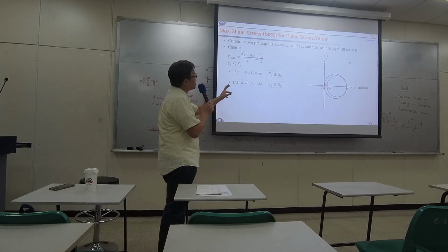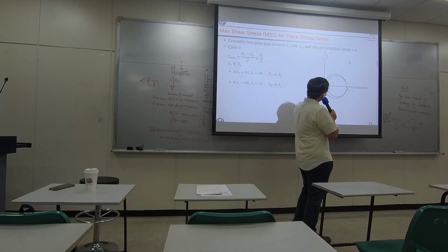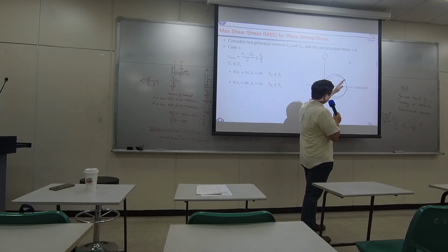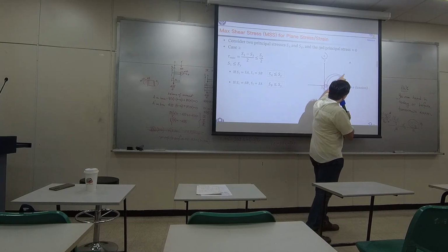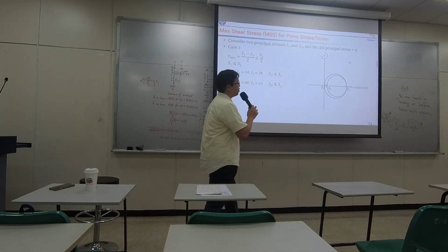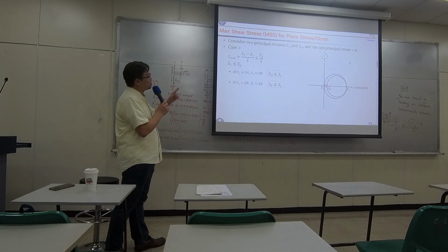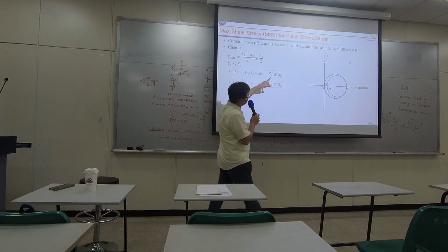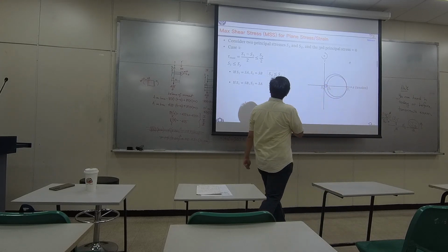So in this particular case, still a plane stress or plane strain problem, where in the third direction we have no stress. But when you draw more circles like this along each plane, you will realize on the 1-3 plane, we do have a greater Mohr circle with greater shear stress. So in this particular general case, the maximum shear is in fact S1 minus S3 divided by 2.